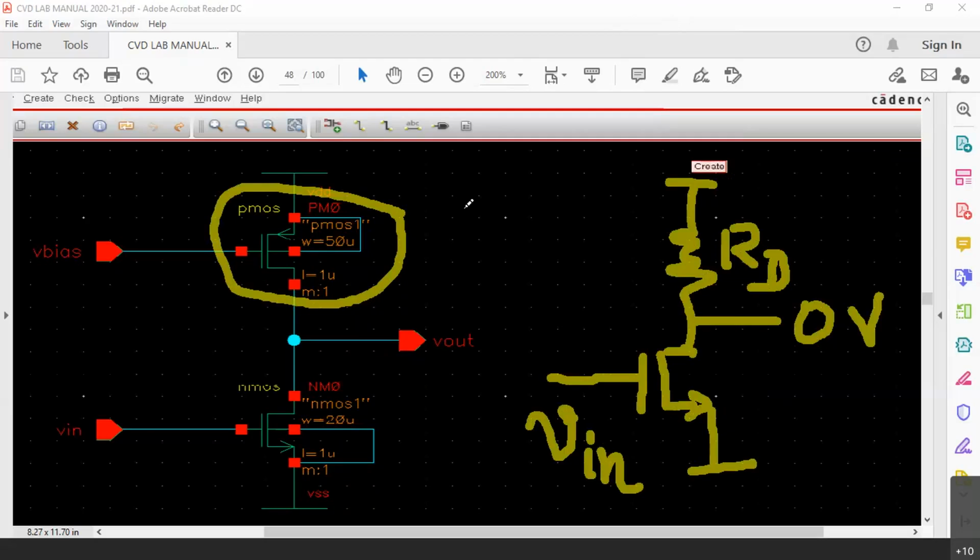In the sense, let me write the characteristic curve of MOSFET. You know it is like this, right? Now in this region, this is the linear region. In this region, its resistance is constant. But this is based on a particular VGS value, right? Based on a particular VGS, you can have different curves.